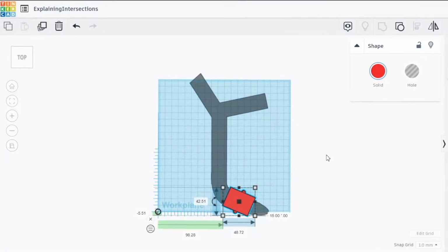Hello everyone, I am Dev Gupta and I will be explaining the steering mechanism of our project. We have a rough diagram of our track and sensors. As you can see, we have a red box as our cart, and we have red spheres which are the sensors of our model. The concept is when any sensor detects white light, the wheels on its side start moving, whereas when it detects black light, the wheels on that side stop moving.